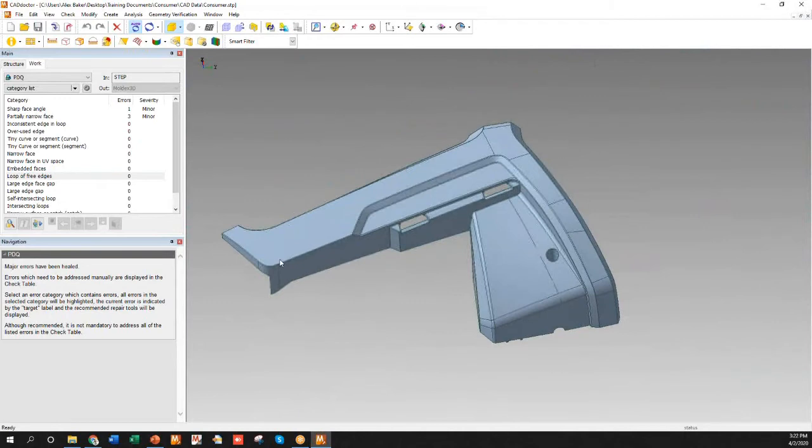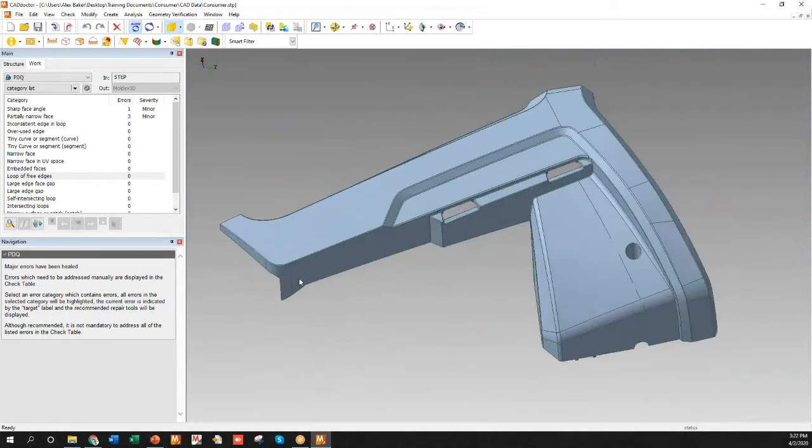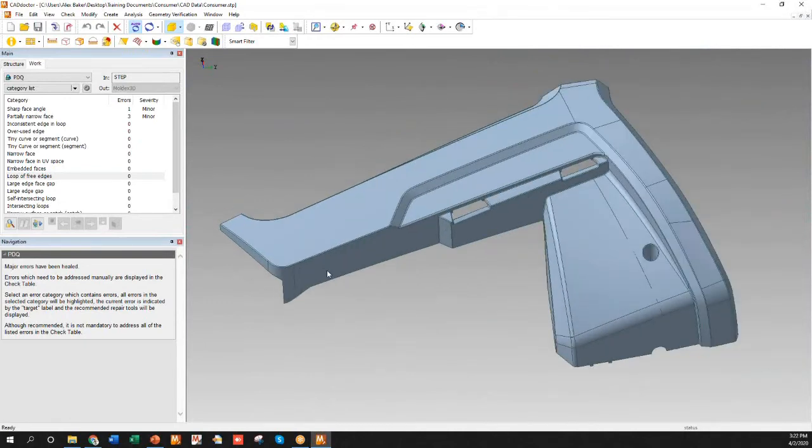That typically happens during the translation process between your CAD system and Moldex3D. Because Moldex3D is tuned to a specific set of tolerances, those tolerances may not match your CAD system, and therefore the surfaces, although they were connected in your CAD system, may become disconnected when they come into Moldex3D. So that's what this button here is used to fix. So typically, import, check, auto stitch if necessary, auto heal, and then the last button here is export.